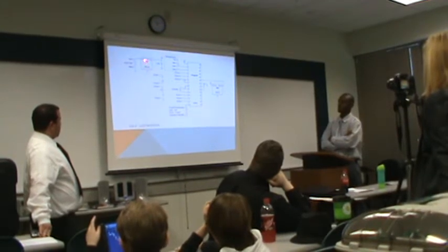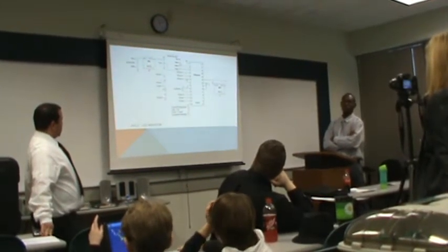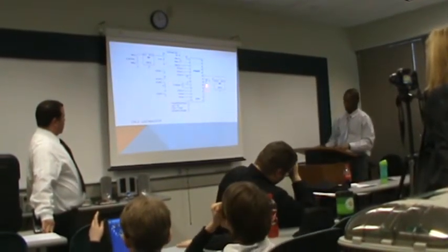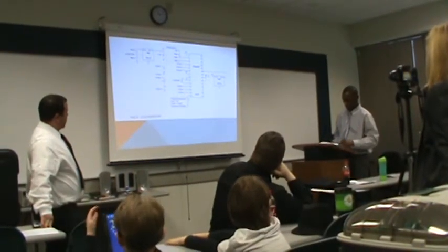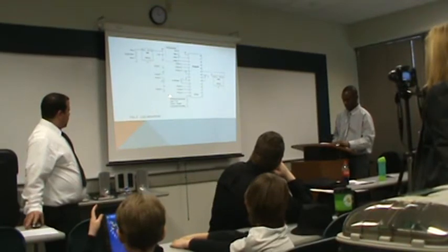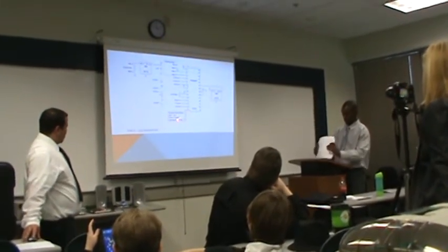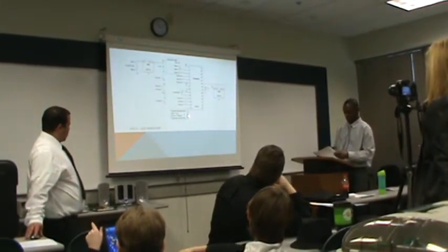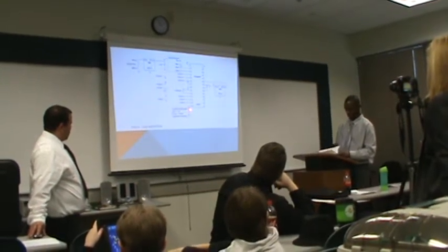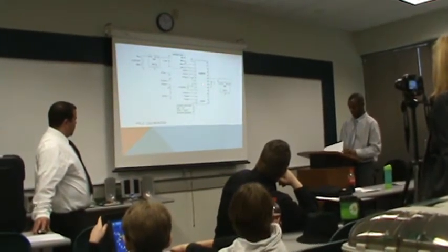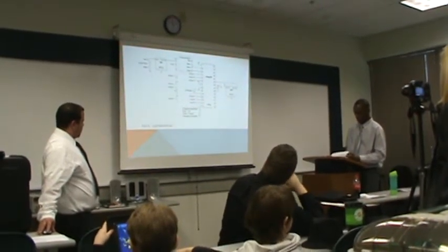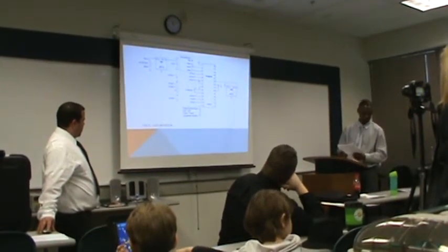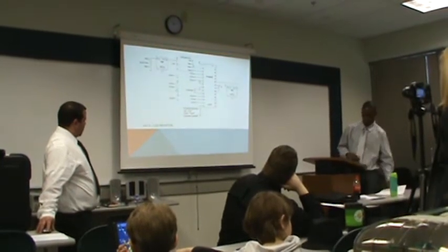And there's the regulator that you saw not too long ago, which provides the whole circuit with the 5 volts it needs to operate. And here is a switch: when we're in program mode, you have to close the circuit so that you can program the chip. After you finish programming, you open the circuit back up so that the program can run.